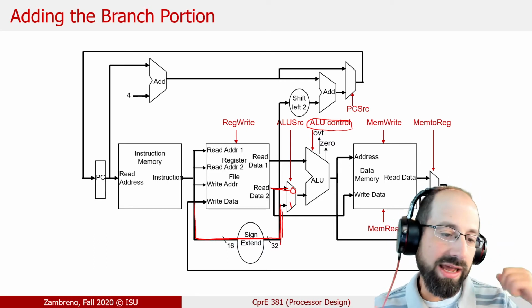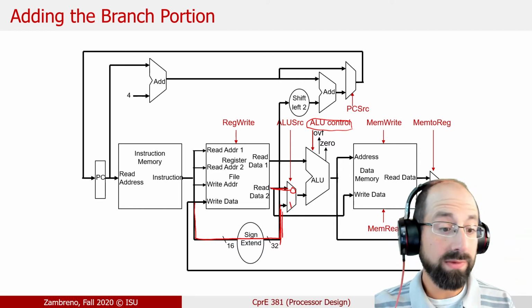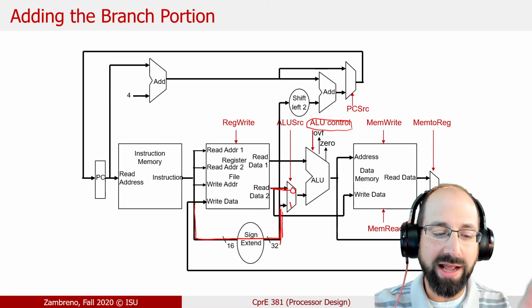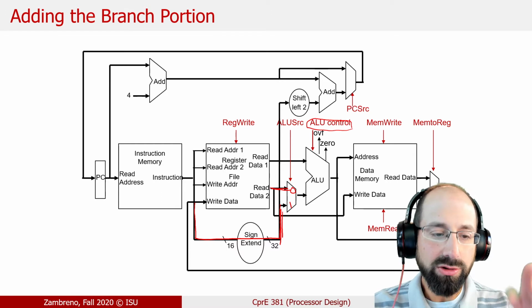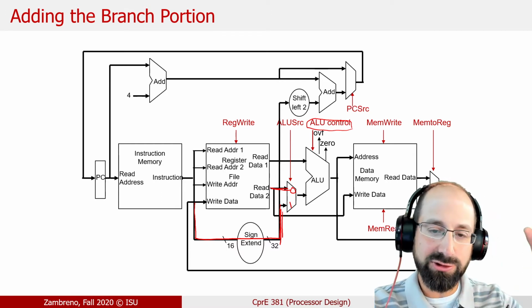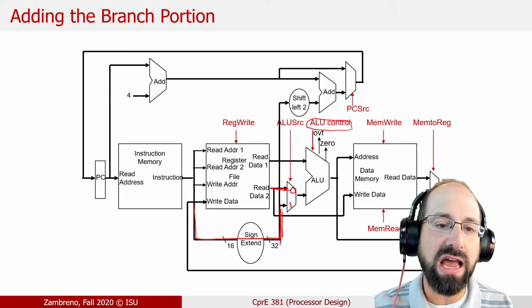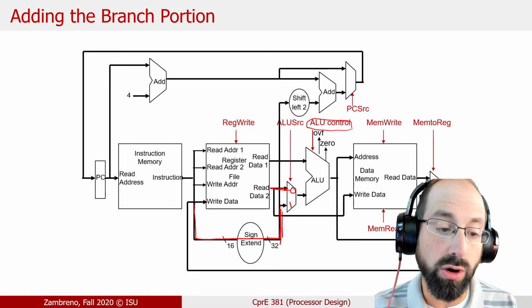Okay, my whatever instruction does not work. Let's look back on the waveform. Oh, it's because this signal should be 1 and in fact it's 0. Why is it a 0? Let's go back to my spreadsheet. It's this signal. It should mean this. We need to change my spreadsheet and change my control. You'll be doing that a number of times. You won't get it perfectly right on the first go.